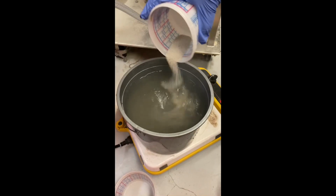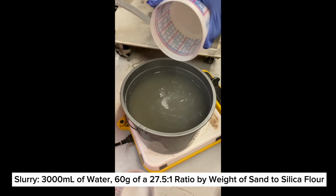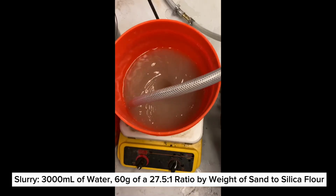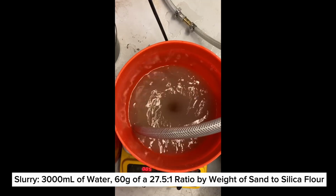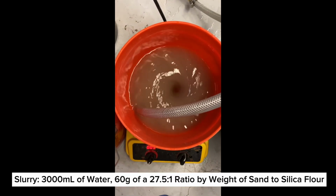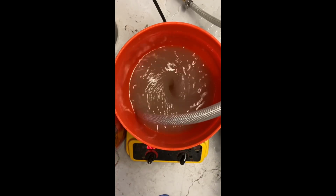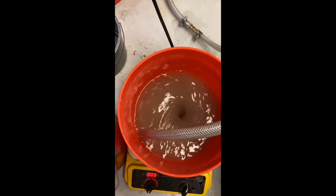To begin this experiment, prepare a slurry consisting of 3,000 milliliters of water and 60 grams of a silica play sand and silica flour blend. The blend should consist of a 27.5 to 1 ratio of silica play sand to silica flour. To reduce particle settling, the batch of slurry is continually mixed by a stir plate.